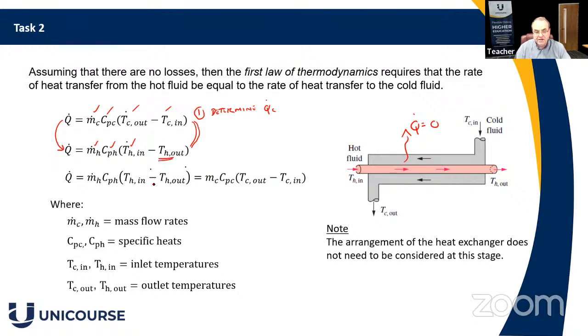So again, look at your answer when you've got the answer to see if it's sensible. Is it lower than the inlet temperature? Then you know at least you've gone the right way. So if the steam is the heating fluid, it goes in at 300 degrees, you would expect it to come out at a lower temperature, like you would expect the cold water to be heated up from the inlet temperature of 15 to the outlet temperature.